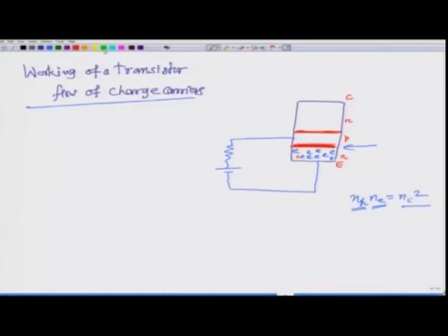So, a lot of electrons will diffuse across this layer and will go from this N side to this P side. They will cross this junction and go from emitter to base. So, remember this is our base. From emitter it is going to base, and of course, the holes will also diffuse from the base side. So, here this is P type. So, you have some holes here, these are the majority carriers, but even then it is a lightly doped material, and therefore, the current is mostly because of the electrons.